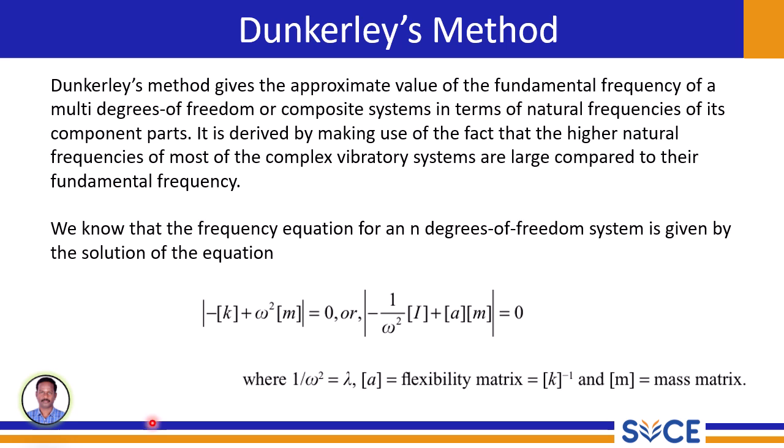The key principle that Dunkerley's method relies upon is the observation that for many complex vibratory systems, the higher natural frequencies are significantly larger compared to the fundamental or the first natural frequency. This allows us to make certain approximations to simplify the analysis.